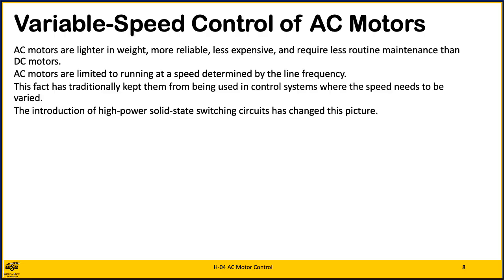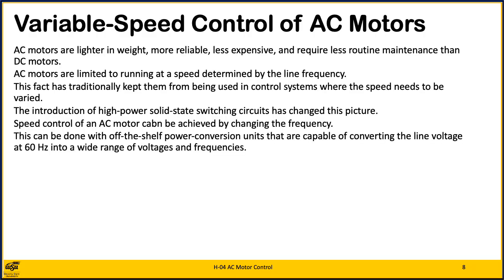The introduction of high-power solid-state switching circuits has changed this picture. Clearly, if you want to fully control the speed of an AC motor, you must be able to change the frequency. This can be done with off-the-shelf power conversion units that are capable of converting the line voltage at 60 Hz into a wide range of voltages and frequencies. A motor control unit, or a control unit plus the motor, is called a drive.